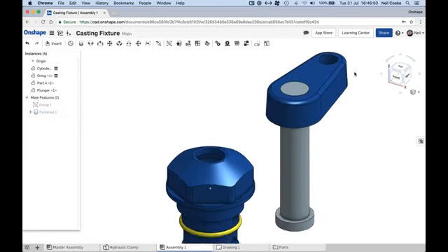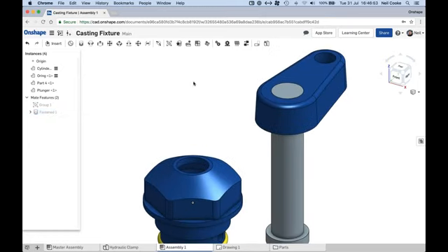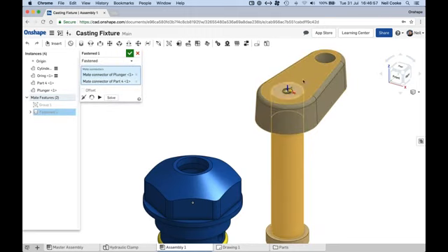Now, if you want to do something like an offset, there's 2 ways you can do that. While you are creating the actual mate itself, there is an offset button there, and these X, Y, and Z coordinates are relative to the mate connector.